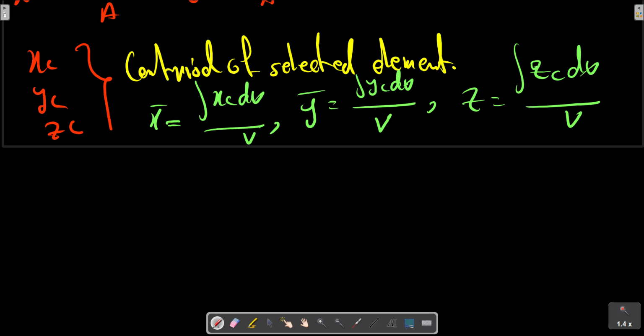Keep in mind the equivalence between the moment of the resultant weight and the sum of the moments of the elemental weights dW to avoid mistakes in setting up the necessary mathematics. Recognition of the principle of moments will help in obtaining the correct expressions for the moment arms xc, yc, and zc of the centroid of the chosen differential element.